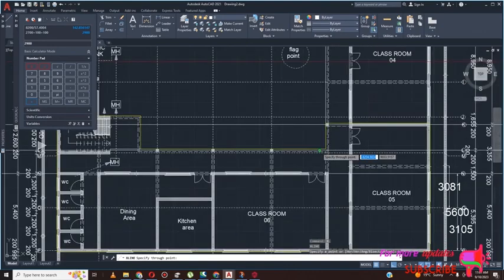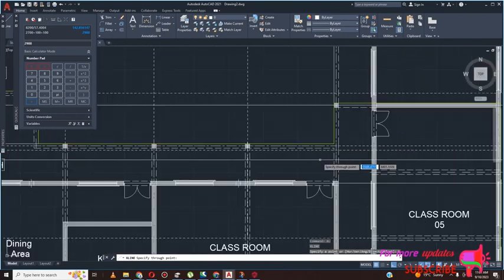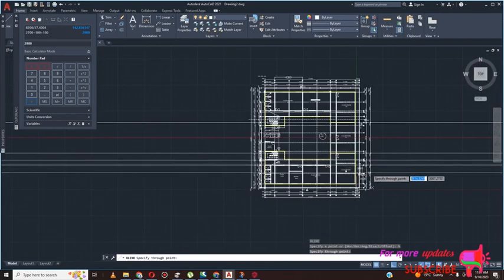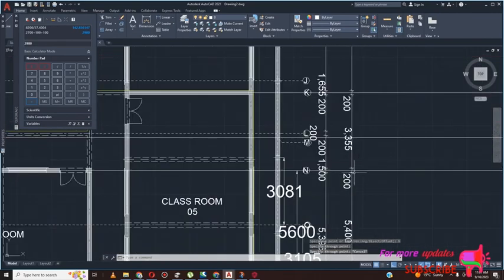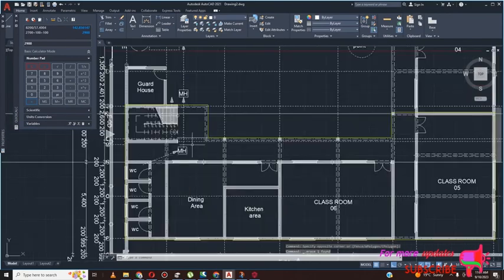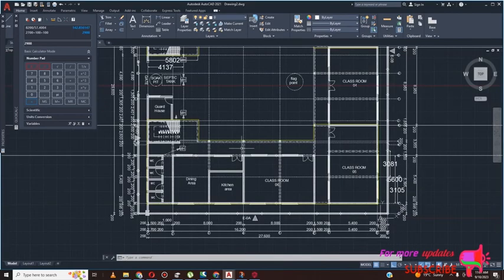Okay. No, can't be. The center line should be here. That grid. So that's why you should be asking for specifications, because even these people are human. But we know that this beam cannot be offset from this one. So I think this beam and this should be on the same line.